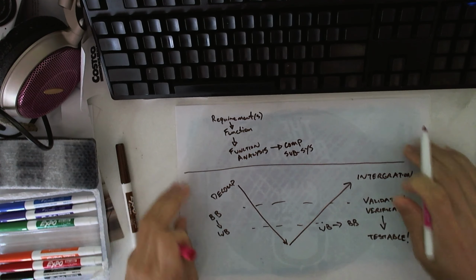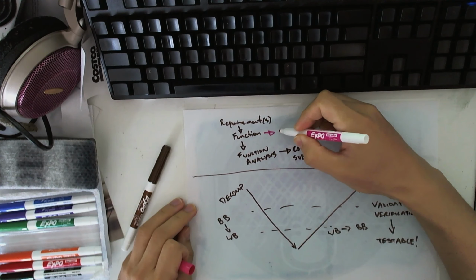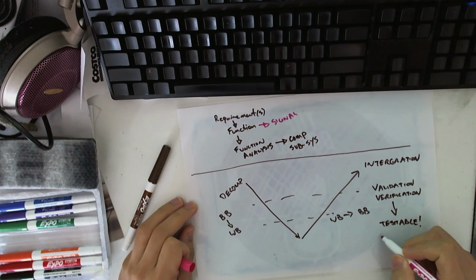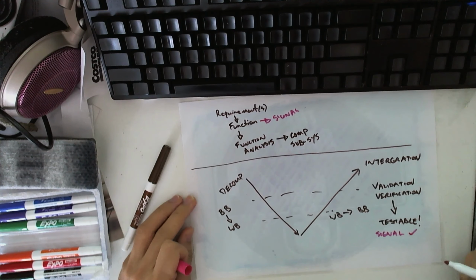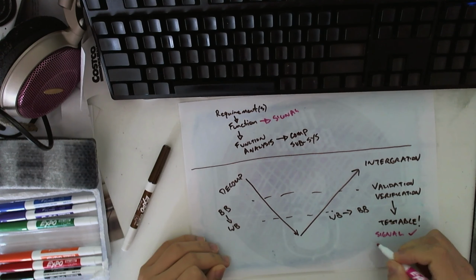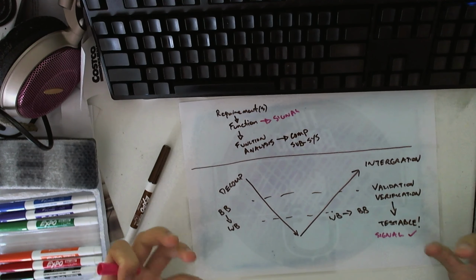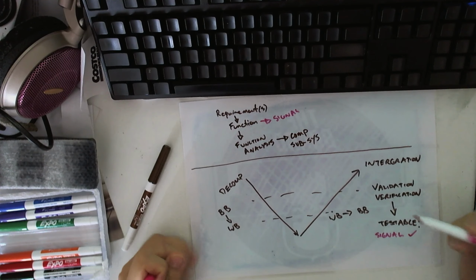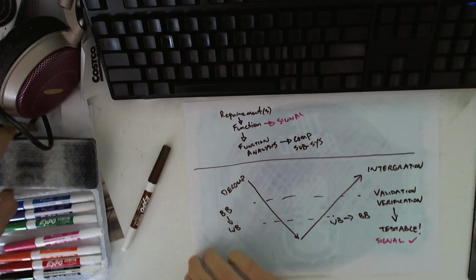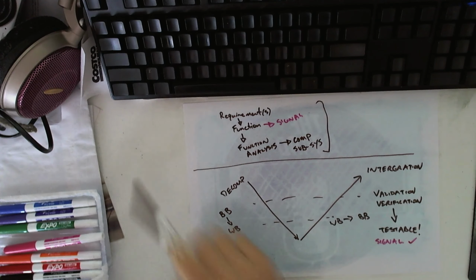So if we take the switch as an example, the function could be as simple as saying it needs to actuate and produce a signal. So there's a signal, right? But then down here, you can say, well, I can close the switch and I have a signal. Tick. But that doesn't mean necessarily that that's a good signal. There is no talk about its quality of signal. There's no talk about its debounce time. There's no talk about how good that contact is or how long that signal period is, and so on and so forth. And so if you don't do that correctly up here, you end up with a bit of a mess down here. And that kind of leads me to going forward into talking about the top section here, at least to start with, on building your requirements and your functions.